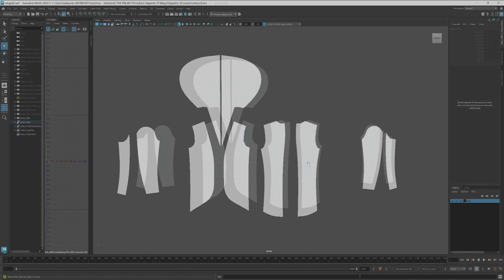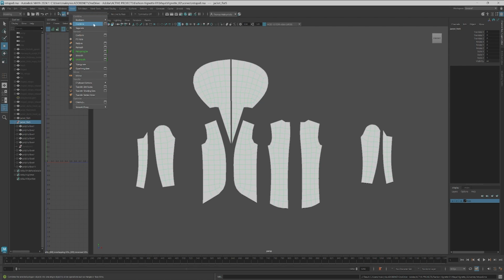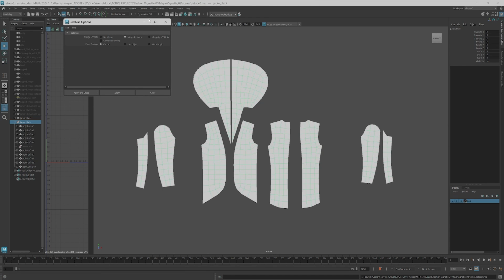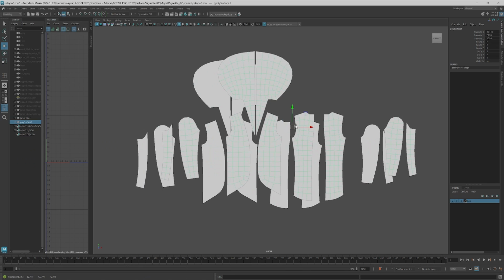if that helps you. After duplicating and mirroring each piece and having them all in place, select the new pieces and choose the Mesh Combine command. This operation makes handling them easier as one object. It's also a good idea to delete the history at this point, as Maya always keeps the history of all operations on each object, and that can sometimes lead to unexpected results.